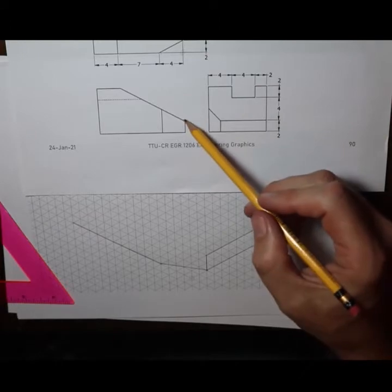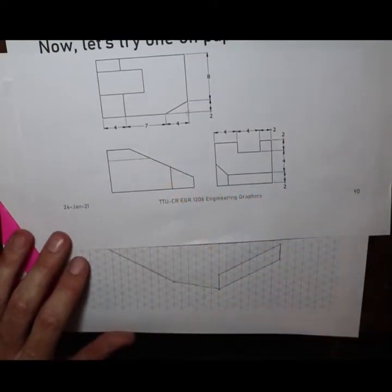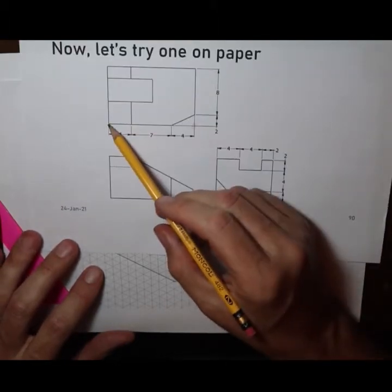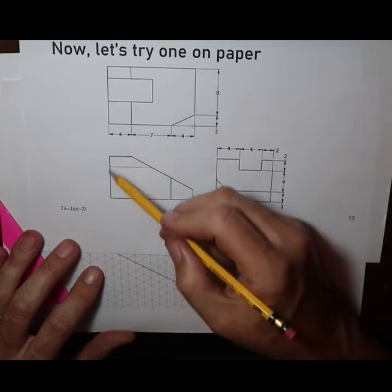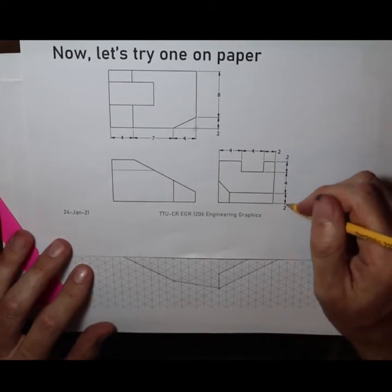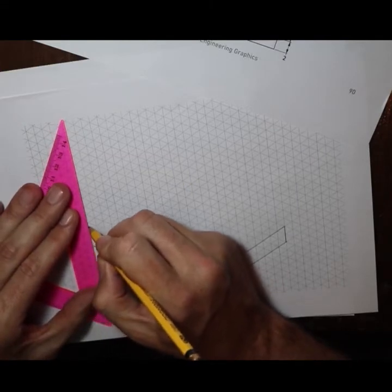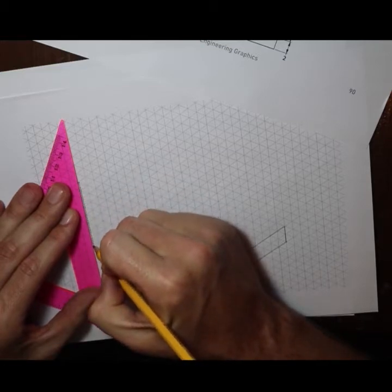Now we can't continue in this direction along here because this is sloped, right? We don't know yet. We have to construct whatever's on top here. So let's go to the other end of our drawing, somewhere over here. We can say, well, we can draw this line because it's parallel, it's straight, goes all the way up. Be this corner here, right? So we say this is 8 high, going straight up. 1, 2, 3, 4, 5, 6, 7, 8. Right there.